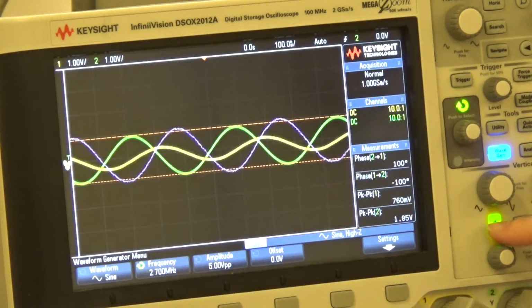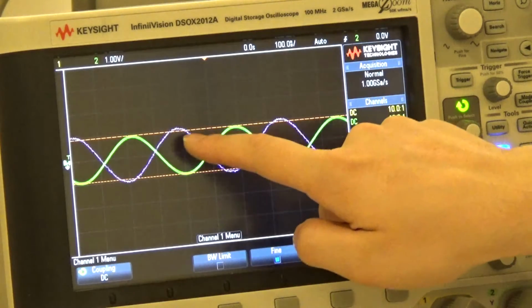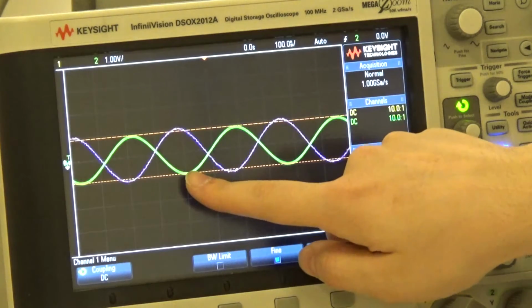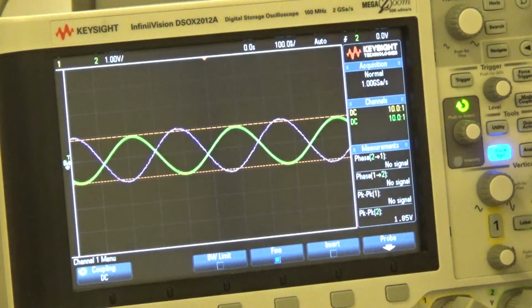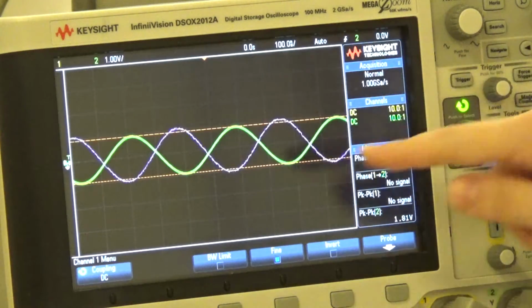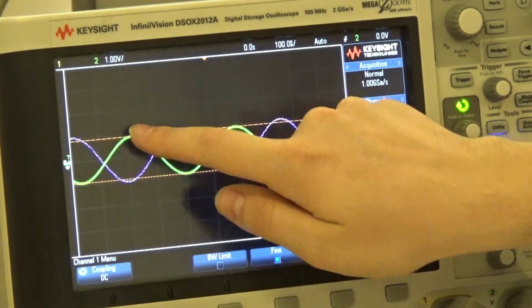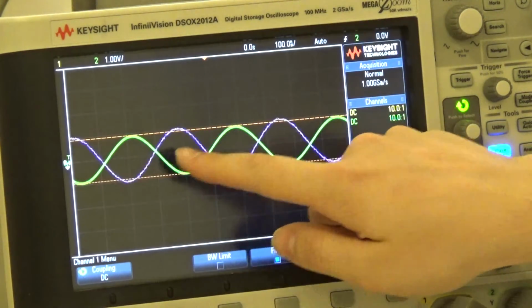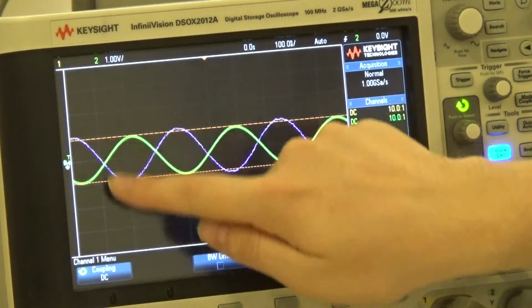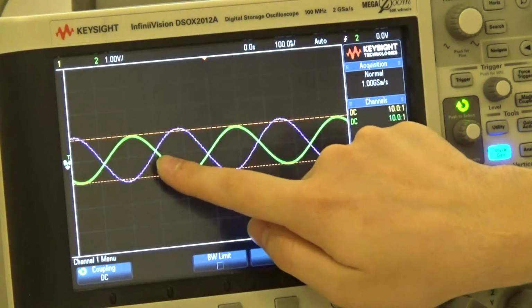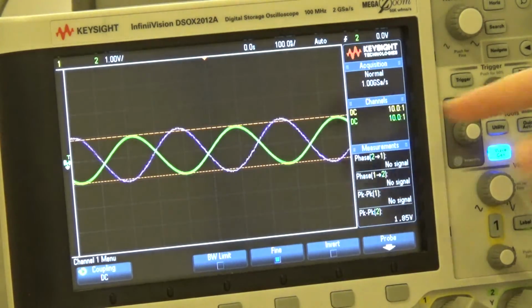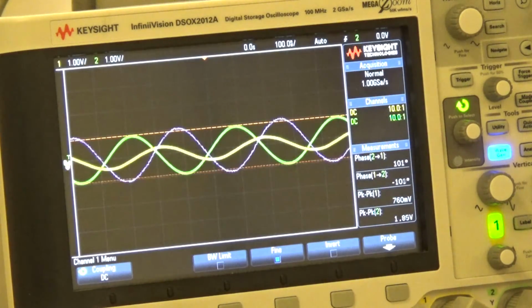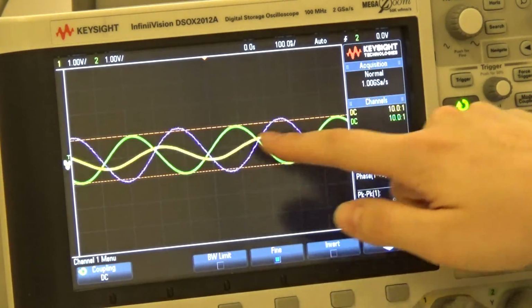As we can observe, the yellow one was the addition of both. So if I close it, I can observe that this purple one is the voltage on the capacitor, and the green one is the voltage on the inductor. So at resonance, we are expecting them to cancel out each other. As you can see, their peaks are nearly equal, their magnitudes are equal, but they have a phase difference of 180 degrees. So when they add up, they should ideally be equal to 0, and that's what we call resonance. But because of the non-ideal effects that we are currently measuring, the total of them is small but not 0.